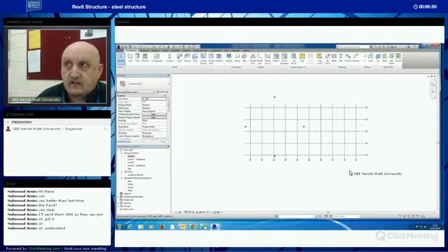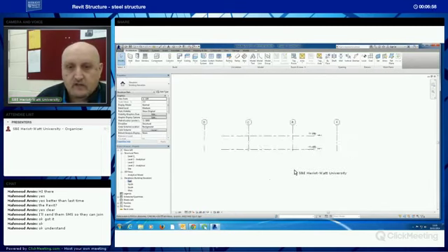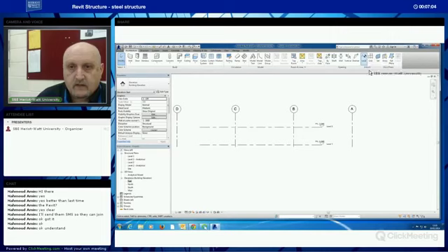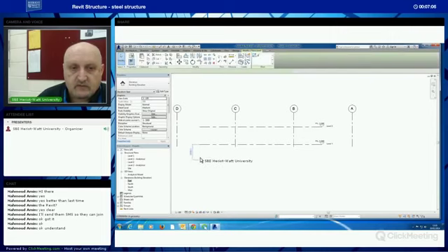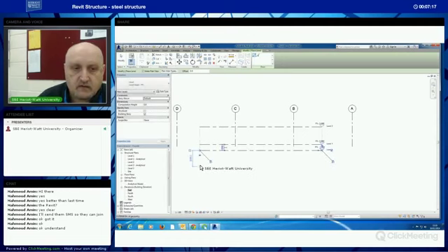Now before I use this grid, I'm going to finish off the setup by putting in the level lines. I go to an elevation view, and I've got a couple of level lines given to me here. I'm going to put some underneath and above. And the level line tool is not available because I'm looking at this building in elevation, a side view. I'm going to put this one down a meter down. I'm going to put this next one down 3 meters from that.